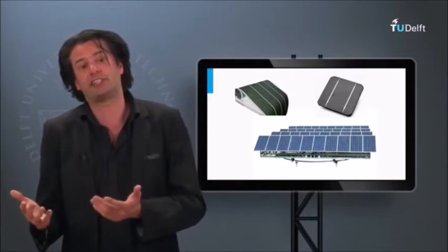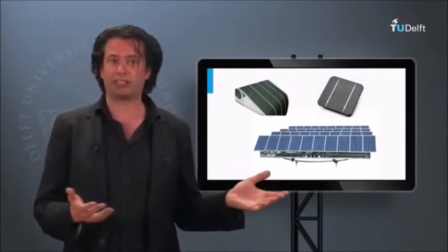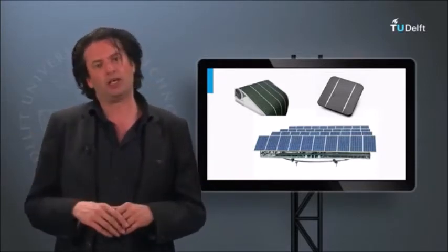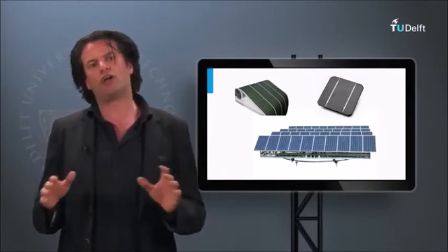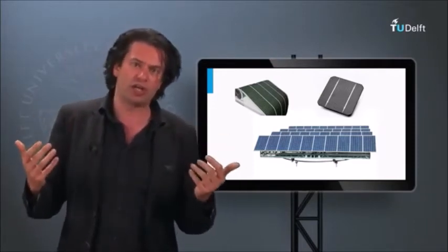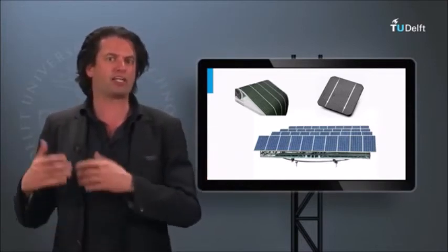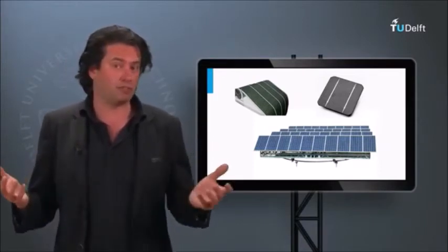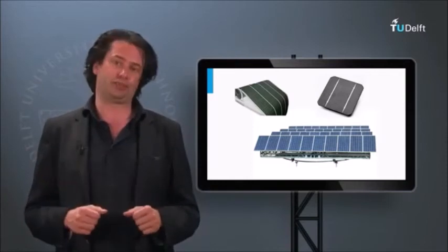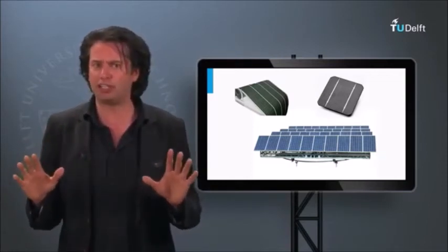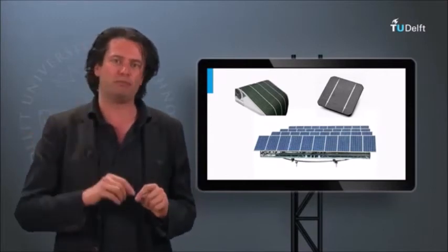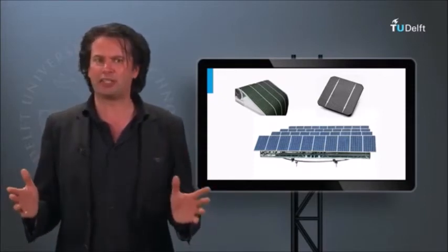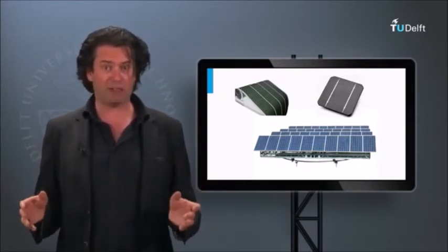However, their efficiencies are far lower compared to some of the best crystalline silicon technologies. But conventional crystalline silicon modules are also very bulky. Polycrystalline silicon modules cover a lot of area. Monocrystalline modules are more area efficient but are more expensive. Amorphous silicon modules are cheaper, lighter and sometimes even flexible, but give poorer yields. So there is plenty of optimization to be done just for the choice of your ideal PV module for your system. The optimum choice will of course depend on the location, ambient conditions, the budget you have, among other factors.